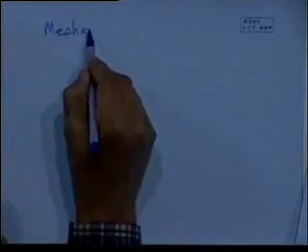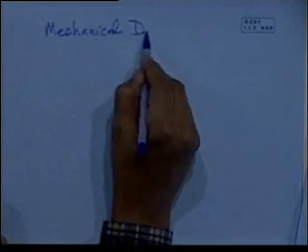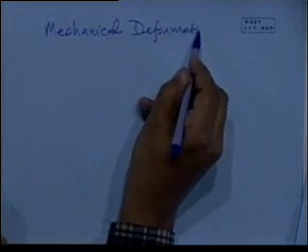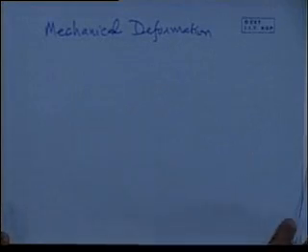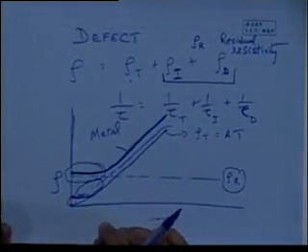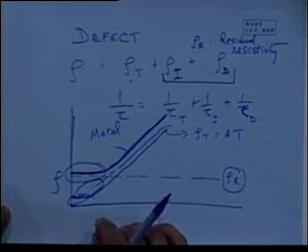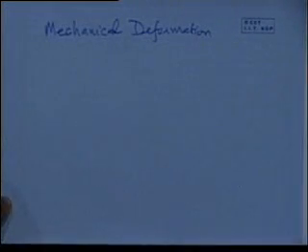The other thing also, since it's defect related, what will be the influence of mechanical deformation? Purity I reduce, I can expect there are fewer scattering centers because there are fewer impurities in the material. But what about when I introduce deformation? How will that affect it? We will increase the resistivity. Why? Because mechanical deformation will increase the defects. What kind of defects typically? Dislocations and things like that.